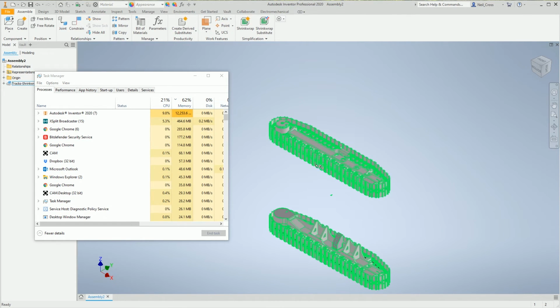So once you've placed this in as a reference part and you've designed your assembly around it, and the assembly grows and grows and grows, you might even have referenced this IPT into other assemblies, not just your chassis, or different other areas of the vehicle. You get an unusable top level assembly, and it's contributed hugely towards that, this shrink wrap file.